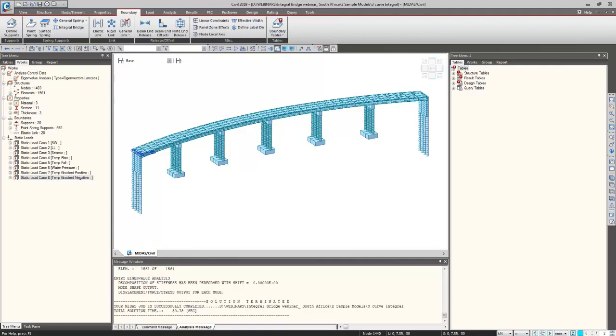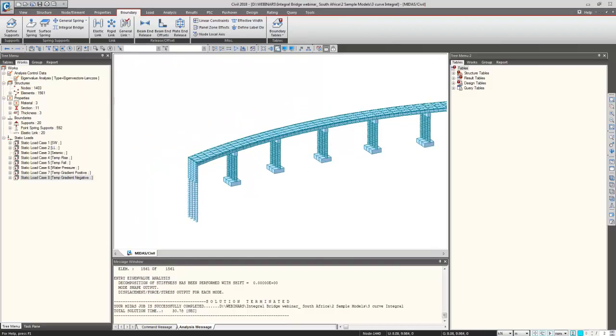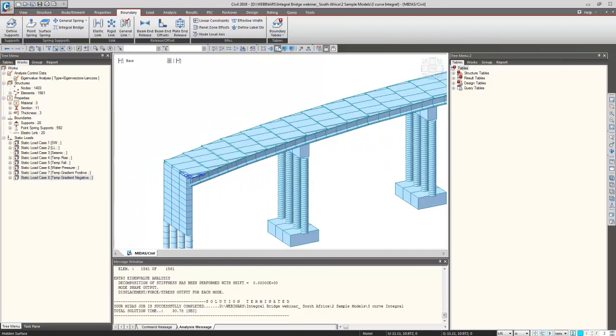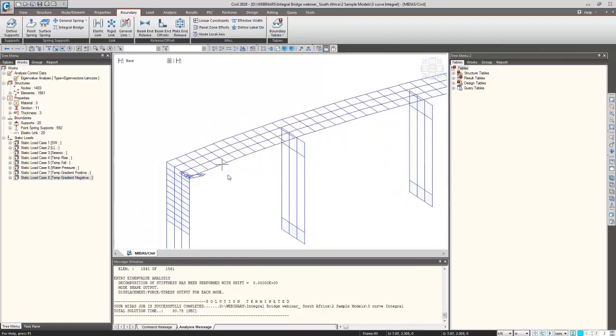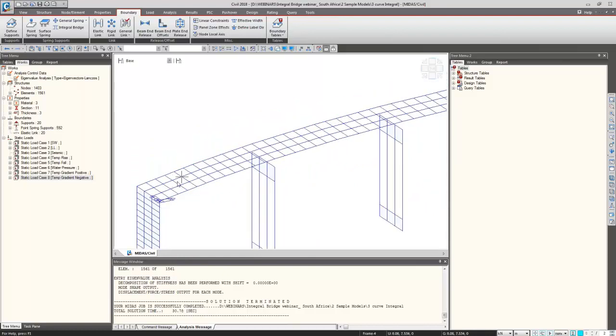So what is the function or the purpose of the dummy cross beams? What stiffness is assigned to them? So this is a question from Mr. Andrew. So this dummy cross beams are required to transversely distribute the traffic load. So you can refer our help manual where the figures are given. So what happens is the load should be transferred to the deck and from deck to the girders. So for this you need to have this cross beams in the moving load definition.